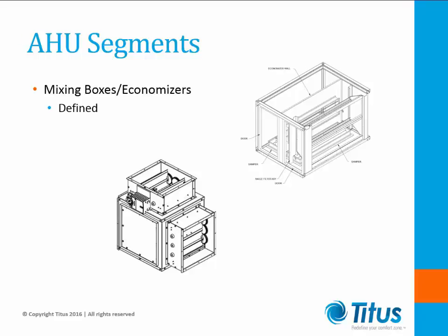It consists of two dampers whose operation is coordinated to control a fraction of the outside air in building supply, while maintaining the supply airflow rate constant. There may be two different ways of incorporating mixing boxes into a system. The first is simply within the air handling unit, or the second, which is applied to the ductwork. The ductwork install may serve its purpose when two separate ducts are not capable of being connected at the air handler.